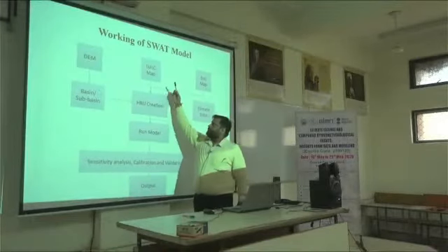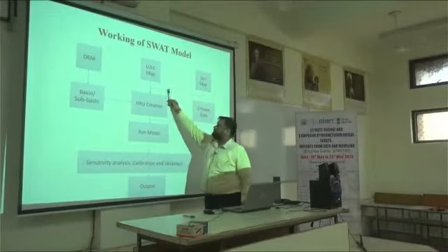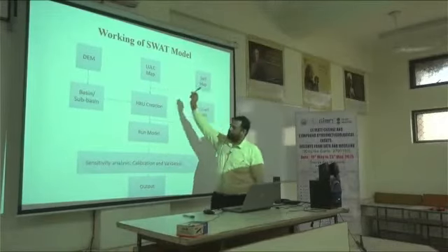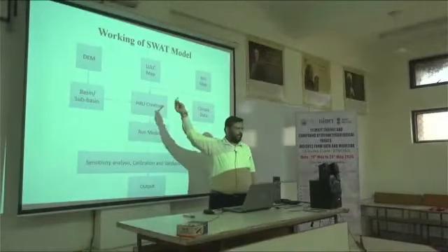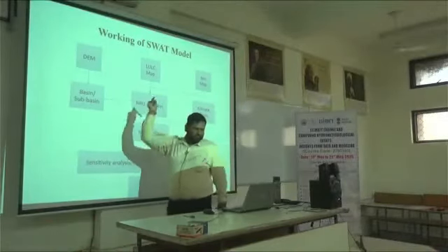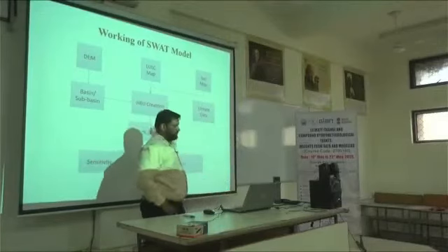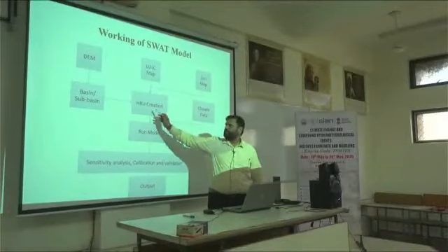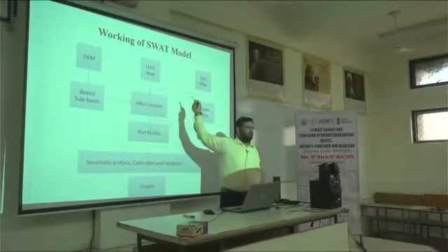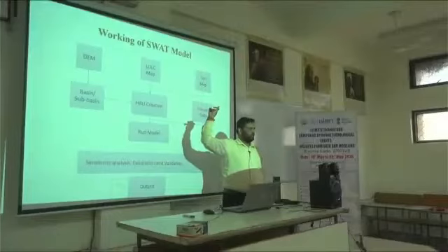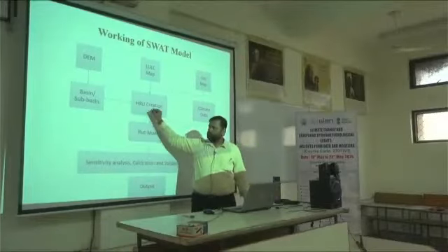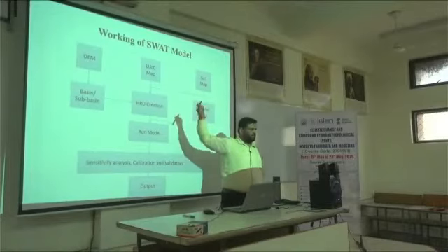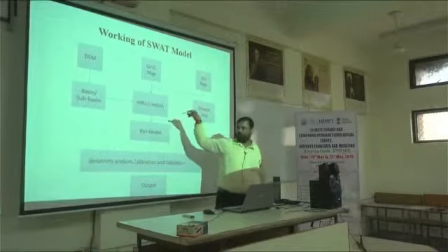Then it will use the LULC map, the soil map, and the basin boundary to break your sub-basins into smaller units. That smaller unit in SWAT is known as the hydrological response unit. This is the smallest unit at which the SWAT model works.